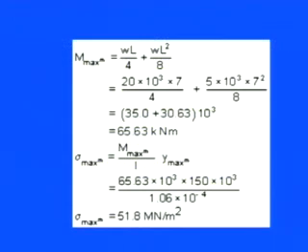That's why the maximum bending moment is nothing but equal to WL by 4 plus WL square by 8. WL by 4 comes from the point load, or the concentrated load, plus whatever bending moment comes from the UDL, so the distributed load gives WL square by 8. If we put those things in, we have W, which is 20 kilonewtons, or 20 into 10 to the power 3, so that is in Newton, these are in kilonewton.